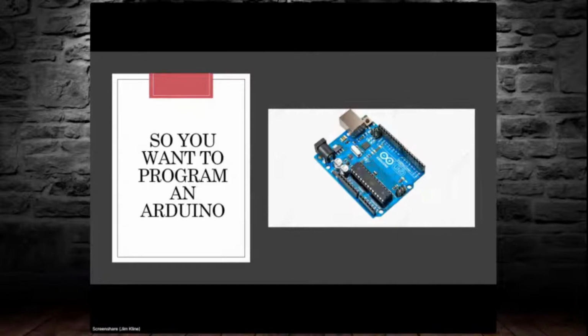The connection strips on each side of the Arduino PC board are female headers that accept male jumpers to connect to external circuitry such as LEDs, lights, switches, potentiometers, etc. Additionally, there are breakout boards called shields that are designed to mate with the female headers that can control motors, servos, and the like. There are many examples of code that are included automatically in the free software download for programming an Arduino. They provide you a proven sketch for experimenting with an Arduino.